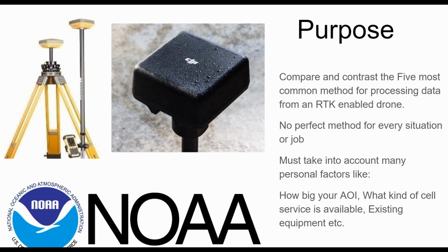What cell service is going to be expected for the majority of your jobs? Some of these solutions require a strong and unwavering cell service connection. If you're going to be working in rural areas or places where you don't know if there's going to be cell service, some of these methods may not be for you. What kind of buildings are going to be in and around many of your jobs? Large, dense urban areas can increase the error of some base stations, letting your live RTK feed vary significantly and adding unnecessary error into your data sets.